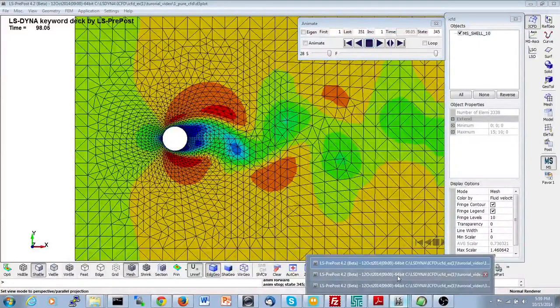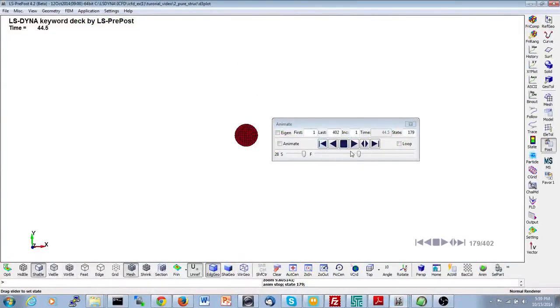So in our case, we're going to use this 2D mesh of a cylinder, which is going to oscillate vertically, which means that it's got a boundary prescribed velocity or motion somewhere. So once we have made sure that both the CFD problem and the structural, the solid mechanics problem, run independently, we can start to think about FSI.